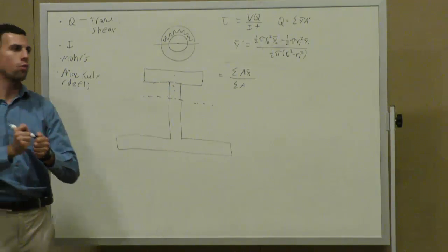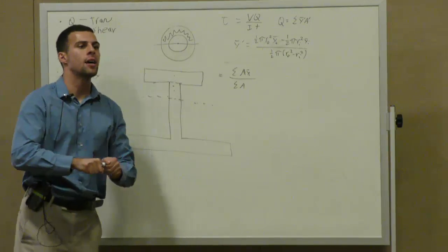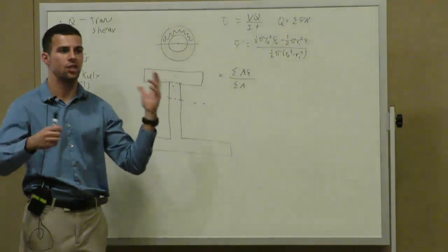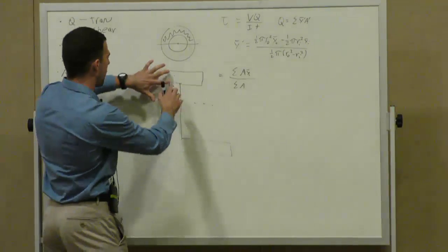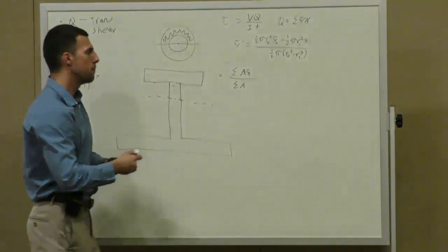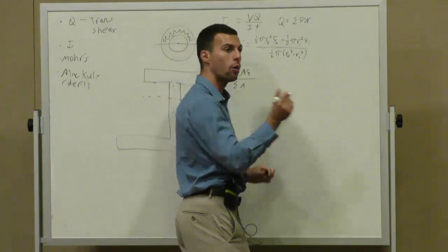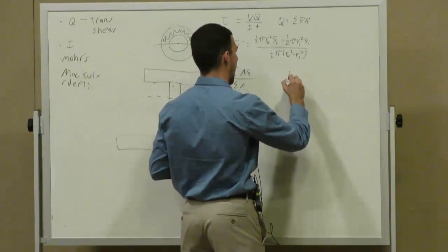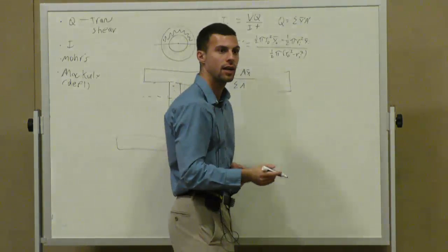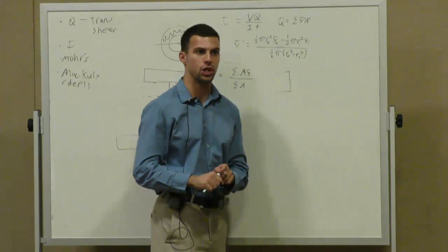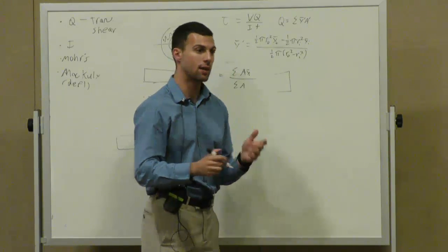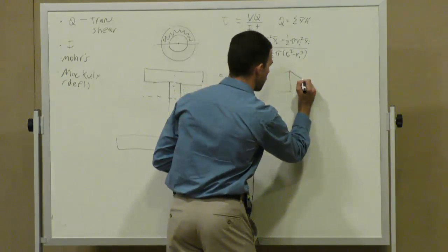And the reason that this happens, right, is that you are looking at a cumulative stress, essentially, of everything above that point, right? Because remember your stress profile. If we look at this from the side, here's a profile view of it. At the edges, what is your shear stress? 0, right? And we maximize at the neutral axis.